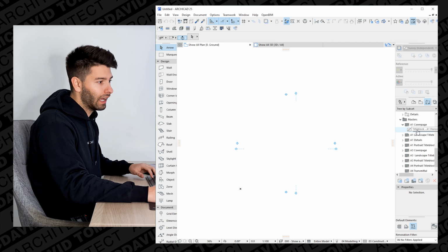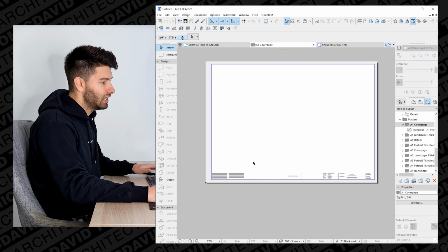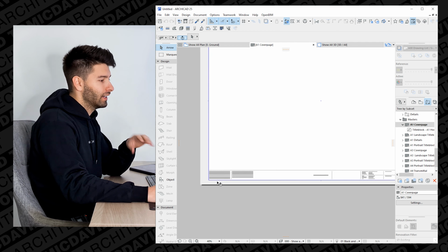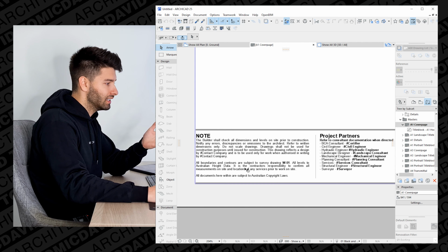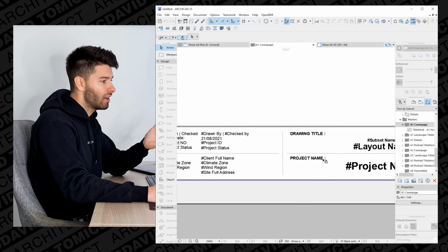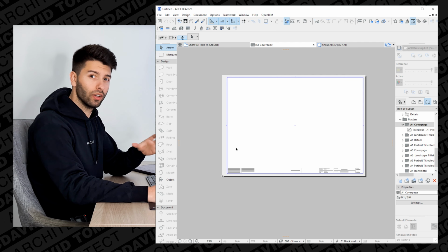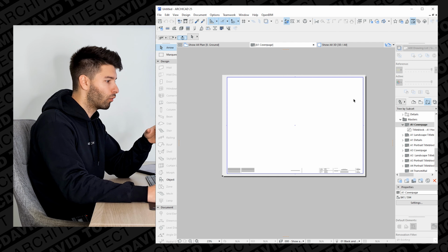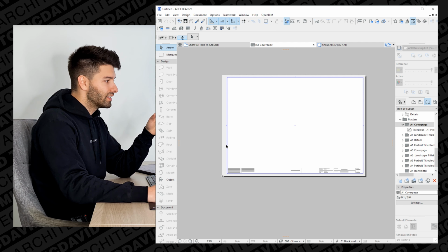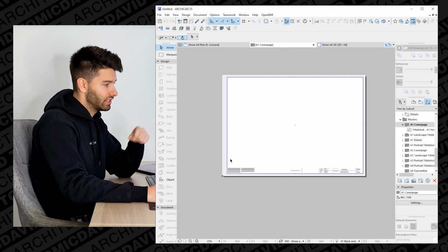So if we drop down our A1 cover block, we can double click on A1 and you'll see it gives you the generic title block from ArchiCAD 25. It is very, very basic. It's very generic. It has some details that are important, but overall, it's nothing special, nothing flash. What you'll also notice is that the bleed markers around the actual border are incredibly thick, more so for stapling on this side than anything else, but it's up to you guys how you want to set it up.